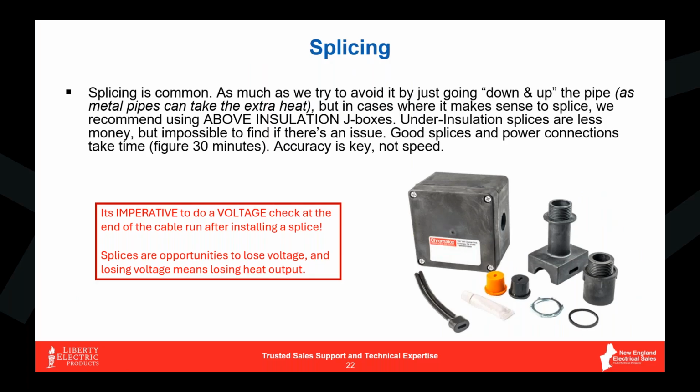tubes that are at the bottom of this kit here that would basically fit over the top of your bus wires and eventually be terminated right to the power source. We always want to make sure that those shrink wrappings are applied correctly, because we don't want arcing going on between the bus wires while the cable's trying to do its thing. So really good splices take some time.